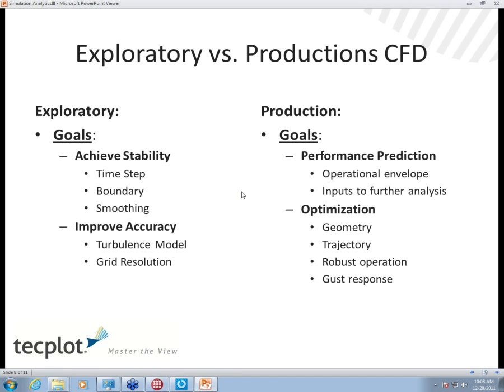So you have to play with it a little on the particular geometries you're dealing with. There are some things you might need to alter to get a robust solution. If you're running an explicit scheme, but implicit schemes as well, you might want to alter your time steps. There may be a time step beyond which it's unstable.